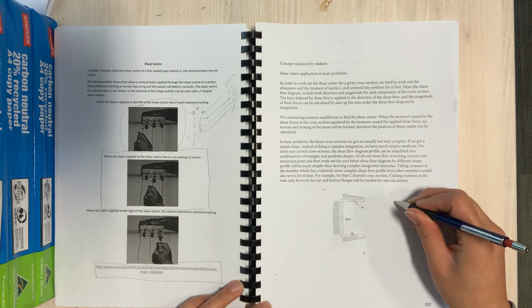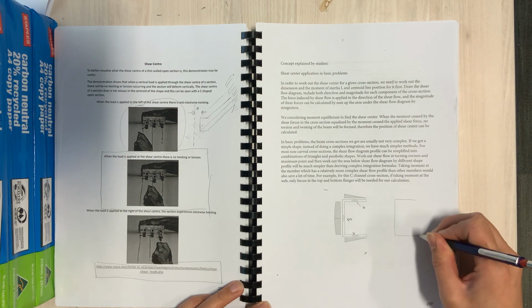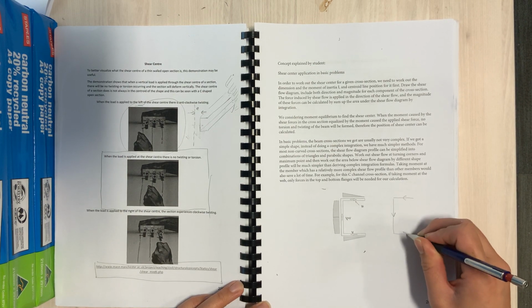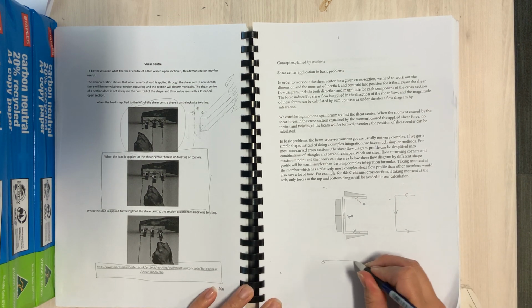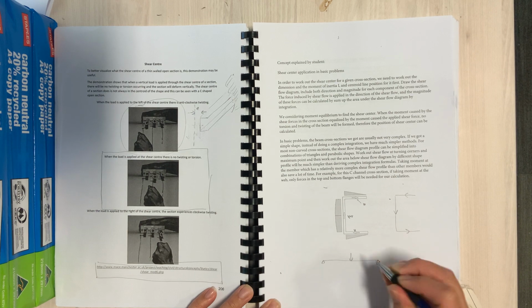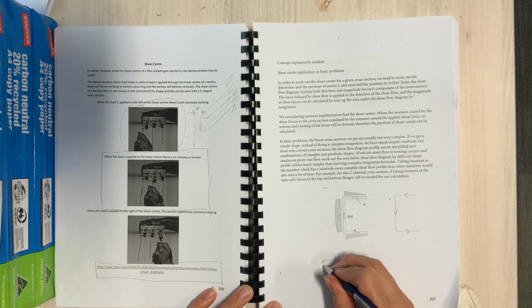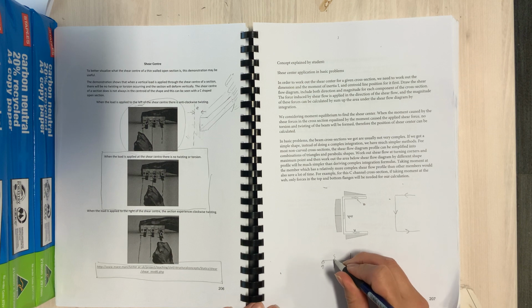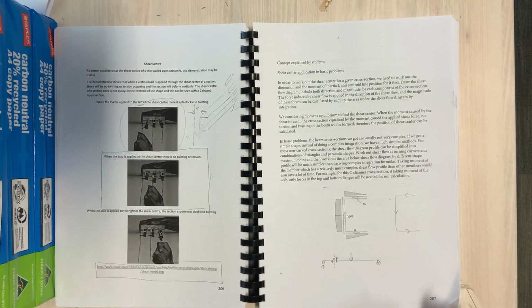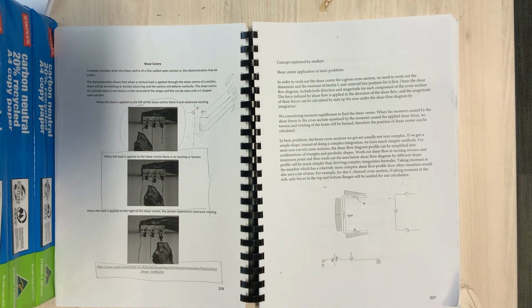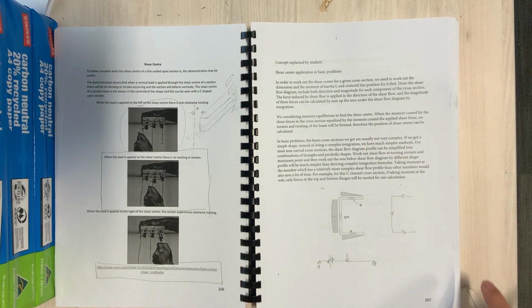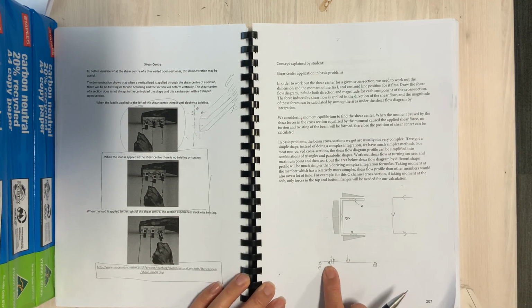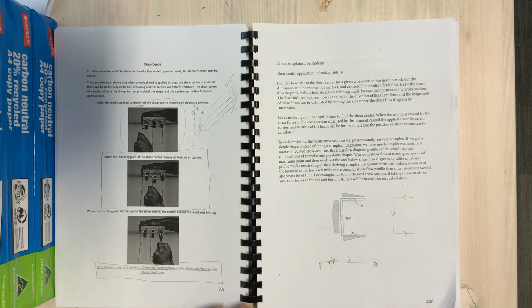So the shear flow, as we said, can either be going this way or this way shown. It doesn't make any difference, and that's because when we've got our simply supported beam under the point load and you take your cut there, you know that the shear force on this side is going down, and we know the shear force on that side is going up. So both of these are the same, they're just on either side of the cut. So don't get confused which way the flow is going. It just depends on whether you're on the left side of the cut or the right hand side of the cut.